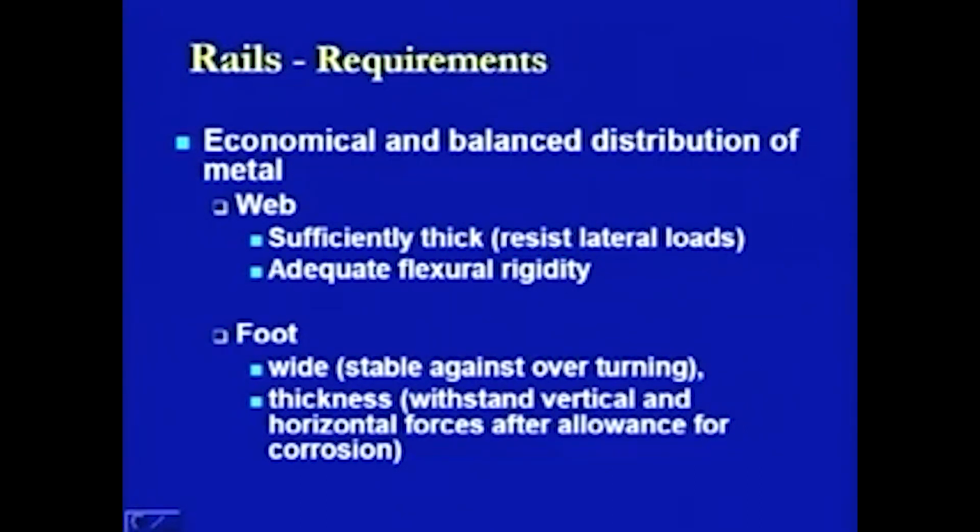The next thing is this thickness. Now, thickness is to be provided because there are stresses which are induced at this level of connectivity. The foot is connected to the sleeper using fastenings. If it is not thick enough, then it will break down very easily and there will be a failure of the system. In this region, it should be able to withstand the vertical and horizontal forces, after giving allowances for different types of durability aspects like corrosion, the effect of corrosion which can reduce the size of the section.